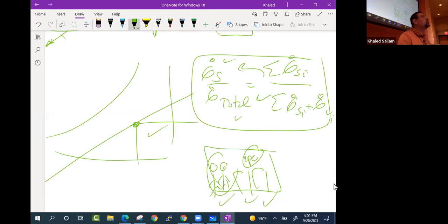Okay? Because it's not just looking at a table, it's also where is the sun? A lot of the load comes from the sun. How many windows do we have? What time of the year is the sun, we are calculating this for, right? How much infiltration is going in? That load calculation is the life of the people working in that field.